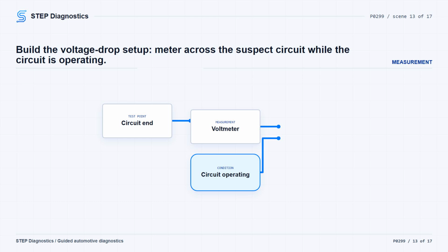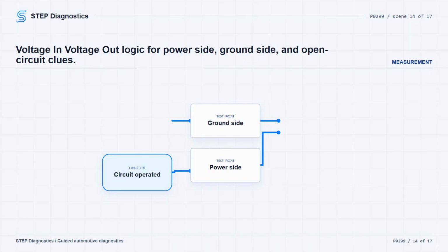For voltage drop measurement, connect the voltmeter at the beginning and end of the suspect circuit, then operate or attempt to operate the circuit so power is available to flow. Follow conventional current flow with voltmeter polarity. A 0-volt reading points to bad voltmeter connections or a component that has not been turned on. A small amount of voltage is normal circuit loss, while voltage indications greater than 0.5 volts indicate abnormal voltage loss.